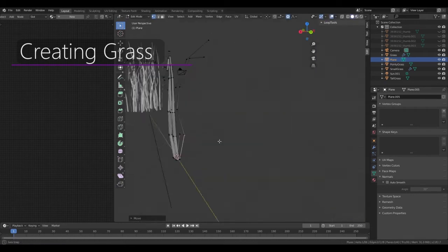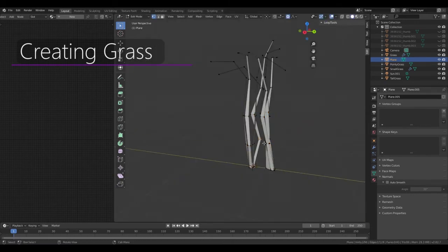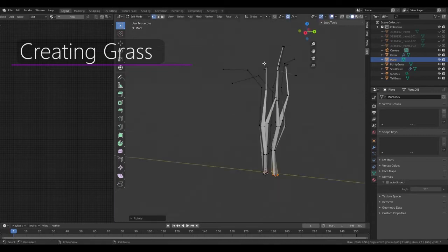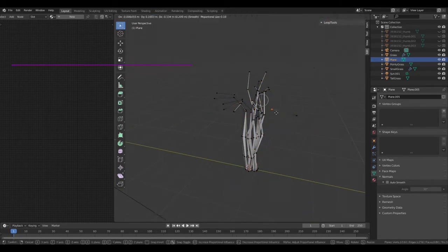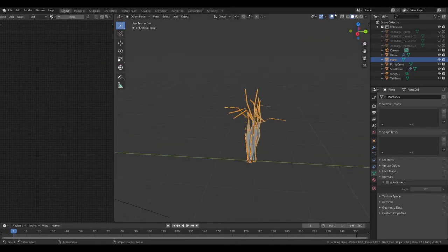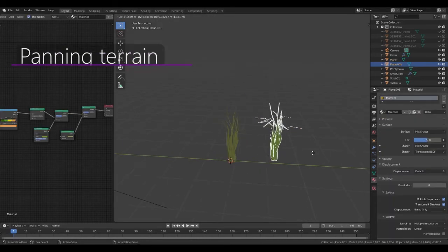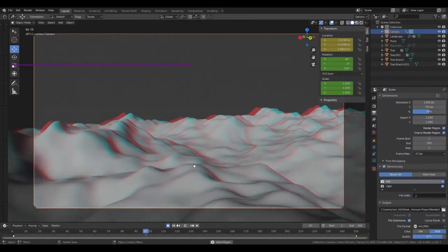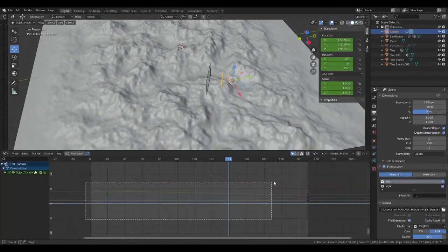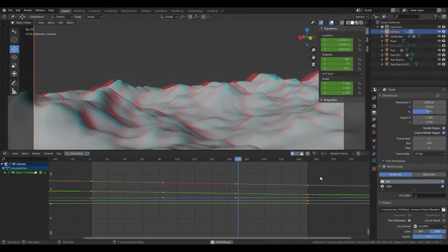These individual grass models could then be appended into a scene project, where they would be applied to a terrain model with a particle system. The models also had a colour ramp shader applied to randomise colour when duplicates were made, representing various ages of the grass. A similar method was used with trees when creating the opening shot.